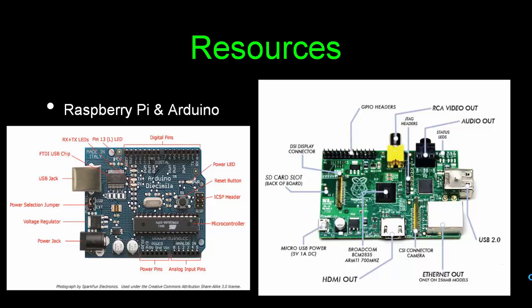A lot of these things come included with it. It's very, very easy to use, and you can program it in Python. So you can set up your Raspberry Pi for your input-output, but you can still use the Raspberry Pi for other things as well. But I think in these instances, what we mean to do is to put these locally at the sites we want to monitor. We'll connect them to the network. You'll be able to access them remotely through the IP address.